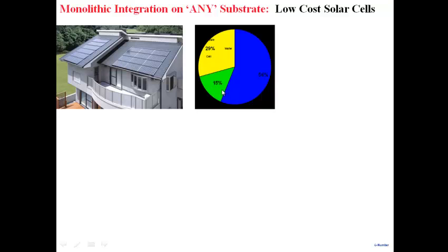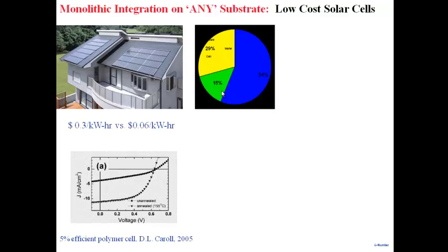And then another fraction comes from taking solar cells and, again, it's a discrete way of making a panel. You make a solar cell separately and then you bring all these solar cells onto a big piece of glass, and you interconnect them in series and parallel and make a module, right? So now the idea is that I could use printing to print my solar cells on plastic, or on paper. So unlike a silicon substrate, which is expensive, I'm now making my solar cells on plastic or glass or paper, which is very cheap. So the substrate is very cheap. My processing technology, which is printing, is very cheap, right? And not only that, I don't have to make separate small solar cells and then put them on glass. I can make the module directly on a roll of plastic.